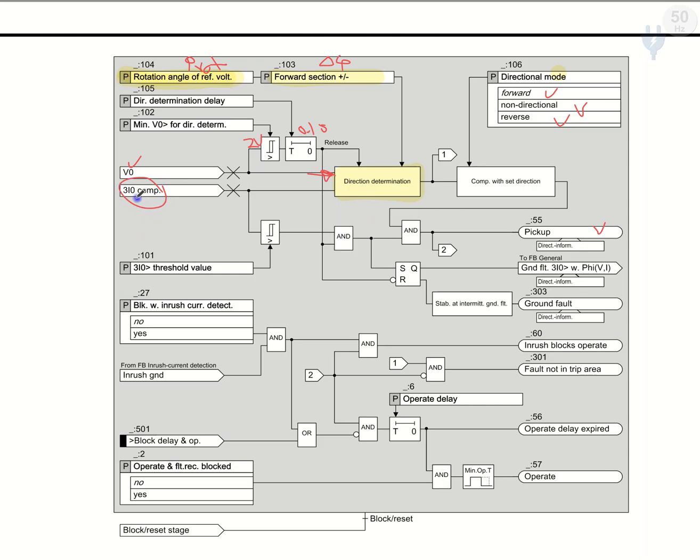You should be aware that the actual burden should be connected to the CTs when you want to know how much zero sequence component you have in the normal condition. Then you give a threshold value higher than the normal condition, the amount at which you want it to trip when the zero sequence value goes beyond it.